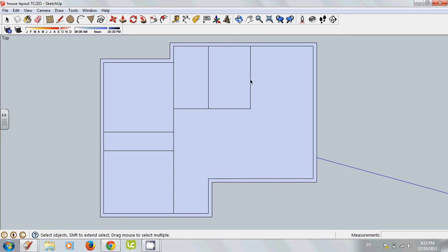And where we live in this part of the world, we're going to use a 2x4 wall. And when we draw that into a drawing, we use a 4-inch wall system because that accounts for drywall and a few other things. In reality, the wall will end up being wider than that because if you have drywall on both sides, you're going to have a 4.5-inch thick wall. But for simplicity, we're going to keep it at 4 inches.